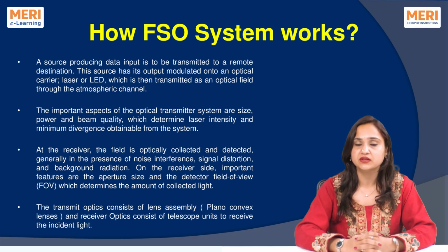On the receiver side, two important factors are the aperture size and the field of view of the detector. The aperture size determines how much light can be collected, while the field of view determines how much background noise may also enter the system.